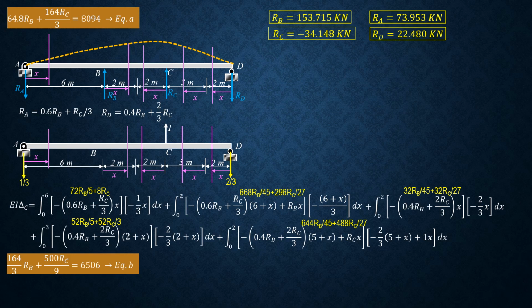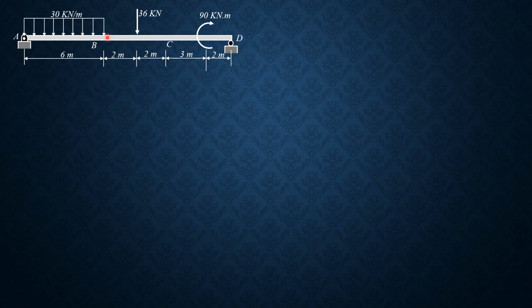Next is by Castigliano's second theorem. We apply a force at B to solve for the deflection. Let's assume upward deflection. Then the reaction at A was 154.8, minus P times 9 over 15. So the reaction here would become 154.8 minus 0.6 of P, while the reaction here is 61.2 minus 0.4 P. It was 61.2 without P, then due to P, it is minus 0.4 P. So that's why we get those reactions in terms of P.